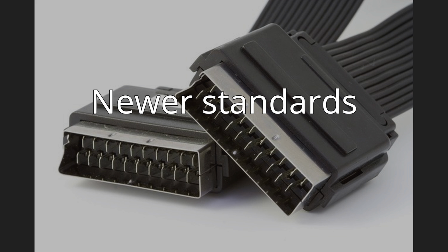However, Scart connection can also support higher definition signals like 480p, 720p, 1080i, if the Scart connection of a device is designed to support YPbPr connection, but this configuration is rare. The same for multi-channel audio, but even this configuration remains rare as it is not standardized.